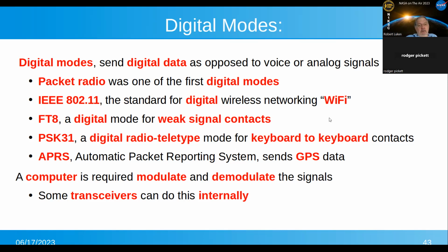The interesting thing about moon bounce, we have a guy in the NASA club that does that. The path loss to the moon and back is 250 dB. Now, remember your dB stuff. That's a lot. So you start off with the maximum of 1500 watts, and that's going to give you about 62 dBm.